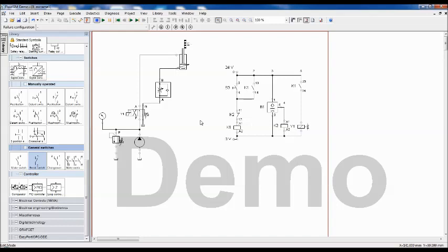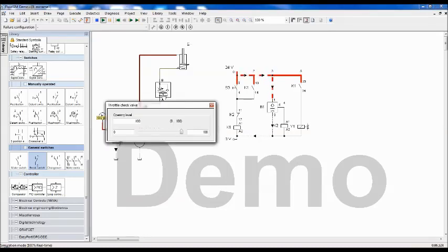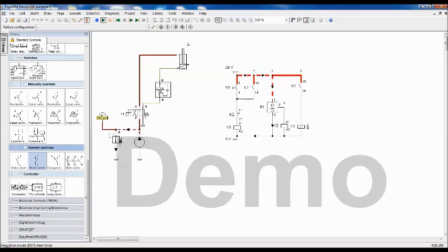Let's go to the simulation. If you press the S5 button once, and the speed is high, so I'll show it in slow motion. If you press S5, the cylinder is moving. Whenever it reaches the B1 sensor, it is returning. Since we are using a throttle check valve, it is controlling the velocity only in the forward direction. In the return direction, there is no control. I'll show it one more time when you operate S5.